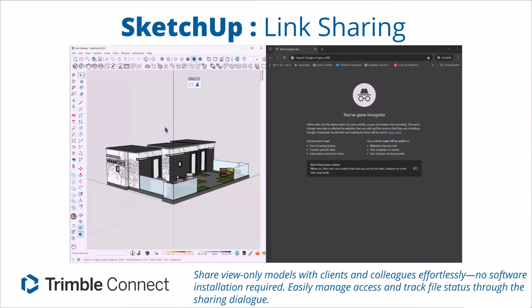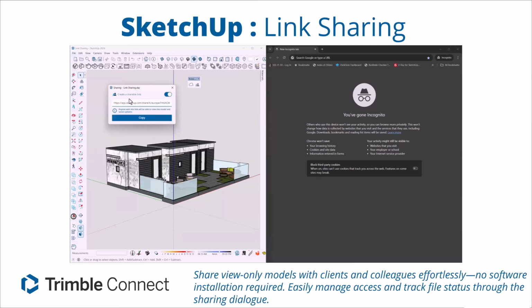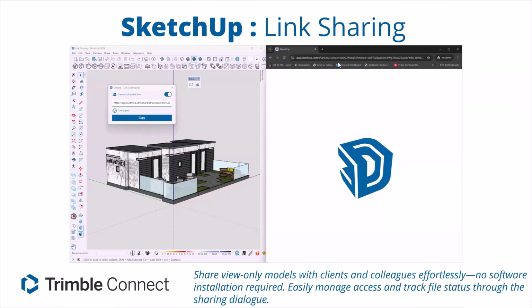What I want to do now is send the link. File, Trimble Connect, share a link, create a shareable link. This can be turned off at any time. Let's click on this again. Let's copy it to the web browser and paste the link. So what we're going to see now is the uploaded shared model from Trimble Connect.